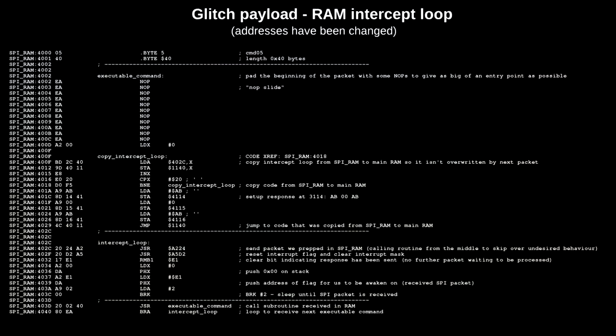Now my goal is to have the ACP execute the code of my choice. Because the 6502 is a von Neumann architecture, all code and data memories share the same address space. From software disassembly, I saw that there didn't appear to be any paging or MMU features. The software in ROM is fully self-contained. There is no EEPROM, and RAM is never used to hold executable code. So there aren't jumps into these areas to exploit, and in fact, it wasn't clear if there's anything preventing code execution outside of ROM. I decided to take a chance and test if RAM is executable.